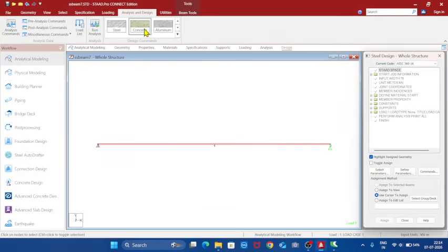select the material. Say I want to design a RCC beam, concrete beam. So click concrete. Here we need to select the code. So current code is ACI code. I want to design as per IS 456 code. So click IS 456. And now, as we told, these are the checklist for doing all the processes. Now this window will become the checklist. That is initially the current code, then select parameters, define parameters and commands.